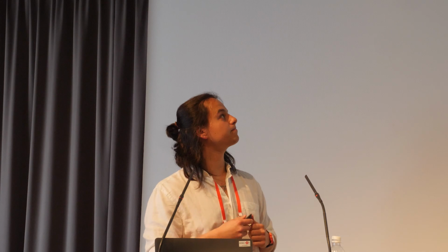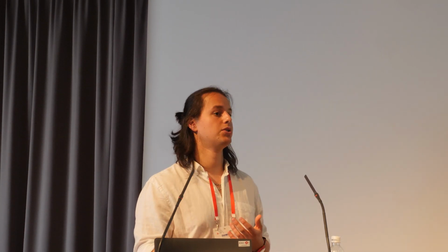So I want to give some final remarks from my side. Of course, this will not be the end of the presentation because Nina still has to discuss a lot of interesting things, but what I wanted to recap here is that Nvidia GPUs offer a cheap way to track hardware activity by reporting these point-wise averages over sampling intervals. And we can use this data to build a generalized dynamic roofline analysis of the algorithm, where performance and operational intensity are seen as time-dependent quantities that vary in the workload, and where we incorporate the topology via this flow graph interpretation of the problem.